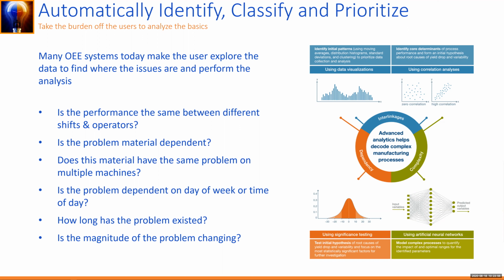Now, the other type of system is a much more old school type of OEE system, where the machine goes down, you have the operator input what happened and why, and then you move on. They're not typically tied to the PLC reason codes and everything else, so you don't get that machine information.